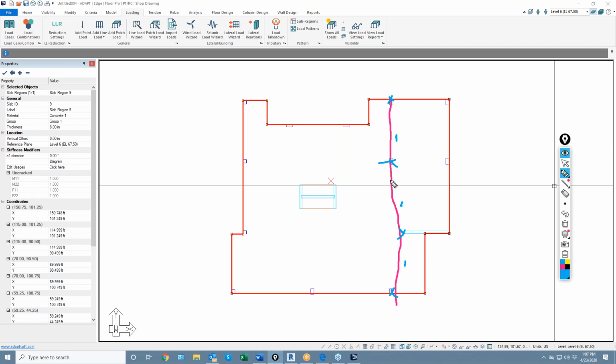And when we add post-tensioning in the slab, the program is triggered to generate the solution, for example, for load balancing percentage. And when you check that, it's going to give you a percentage here. Maybe it says 50%. And that 50% is a function of the self weight and the reserved dead load.